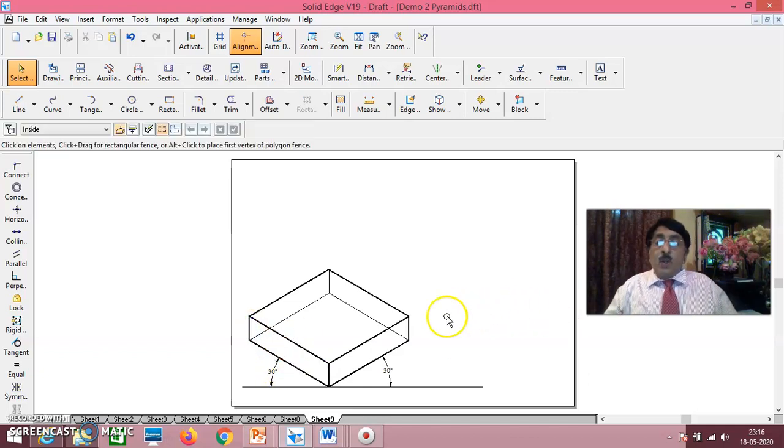In that way, what I have now got is isometric view, because I have not reduced the dimensions. If I take this entire thing and multiply by 0.816, this will get reduced and it will become isometric projection. Now this is isometric view, and if you take the scale and multiply by 0.816, it will become isometric projection.